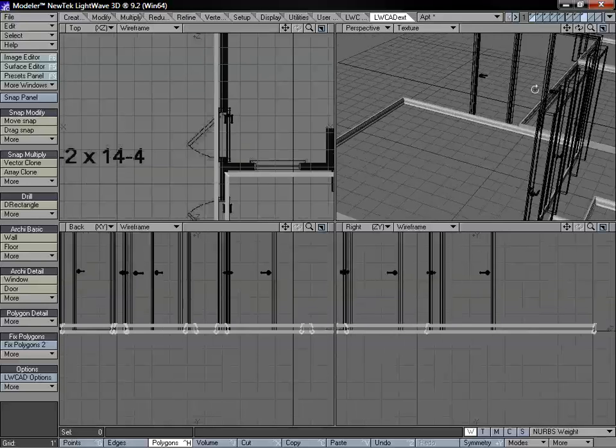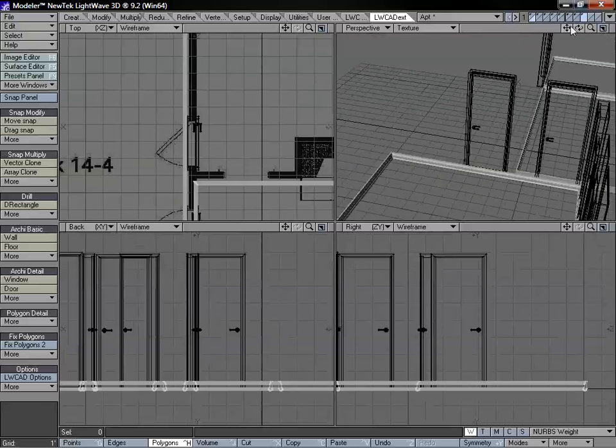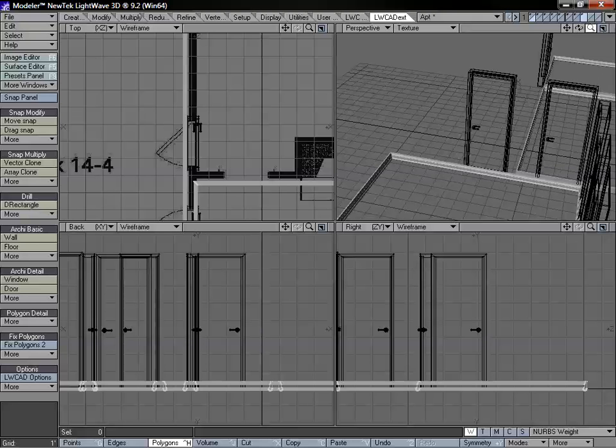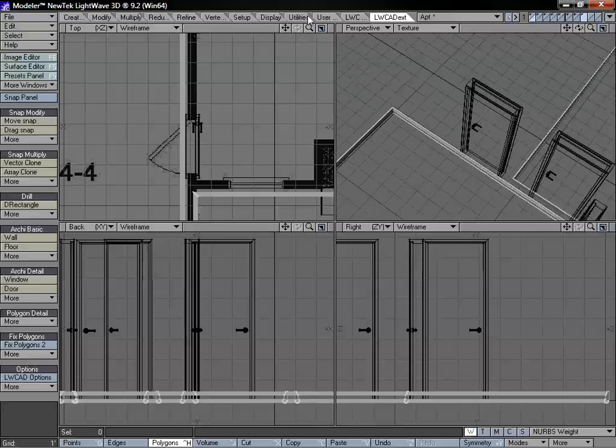One thing we could do is if we created a door that was just the door itself, and then we could use the line tool the same way we selected our trim, but actually go along the entire outline of a room. So we would select the corners along with the bottom of the door, the top, and move all the way around. And that way we could specify trim that's all going to be connected if we wanted to have it like that. And that's just another way we could do it.